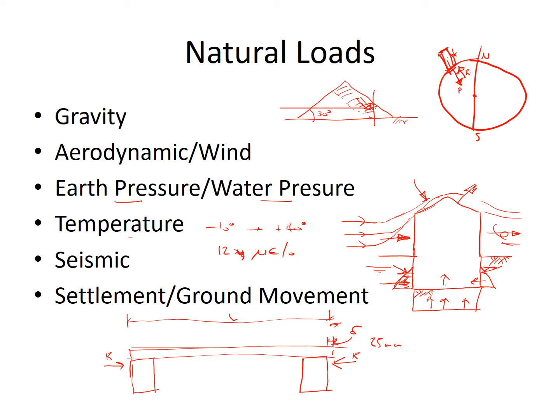Occasionally we do, well, we typically do look towards something called integral bridges in bridge design now, but traditionally, and in most longer buildings, we don't even attempt to resist those loads, because what happens is that this structural element will fail, and this will crack or bend under the extreme loads from this temperature induced expansion.